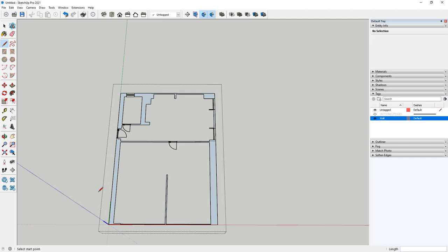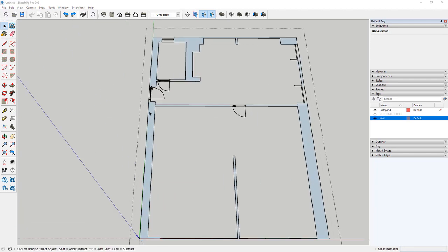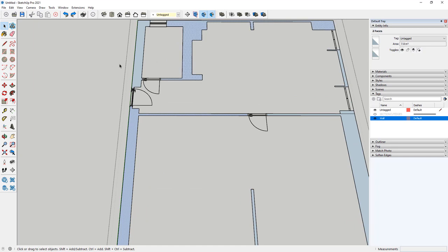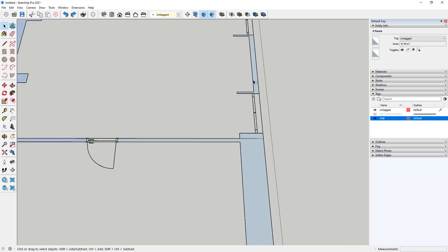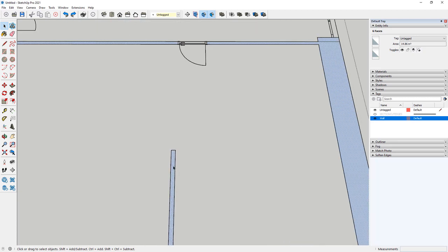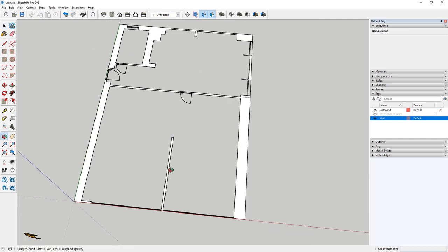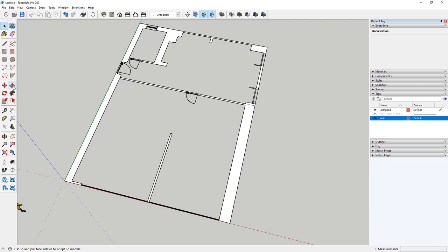The more contours you have, of course, the more time you will need to spend to close all of them to get the surface. Of course, finally I have all the surfaces with the reversed side, so right now I need to manually change each of them. Of course, there is also the plugin that I showed you in the other classes that you can use to reverse automatically by SketchUp all the wrong way planes.